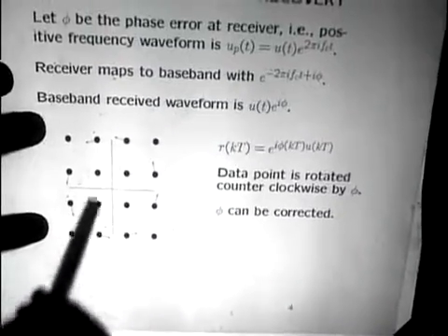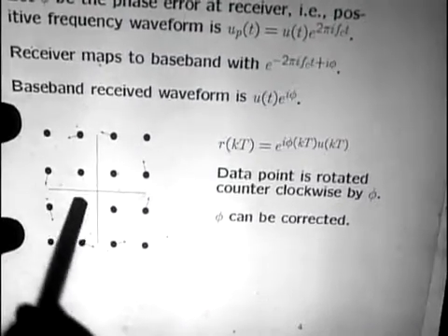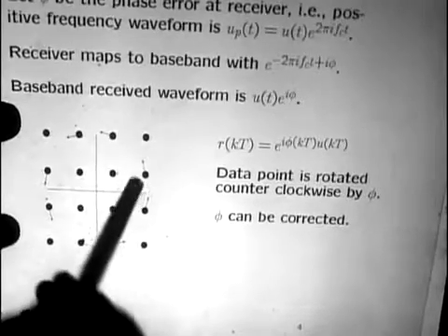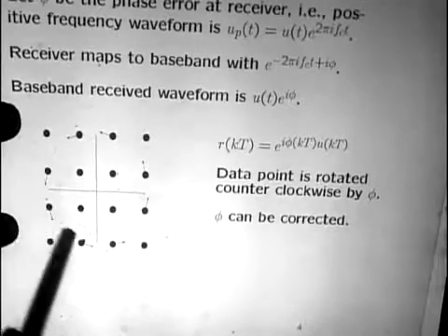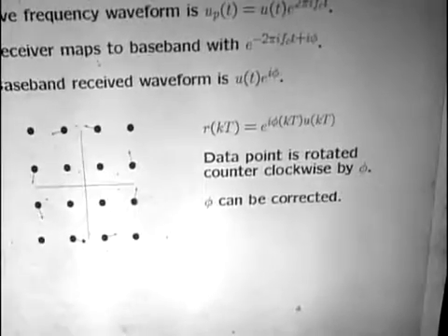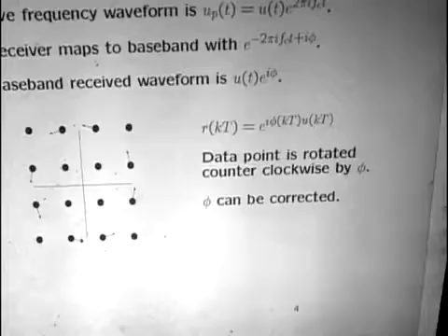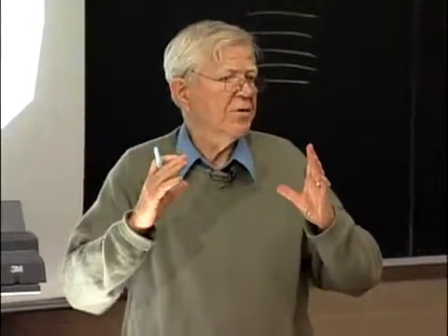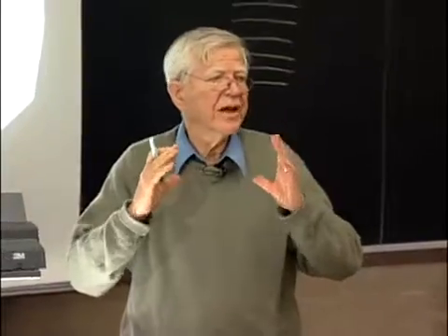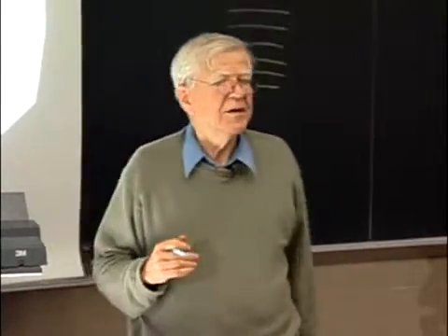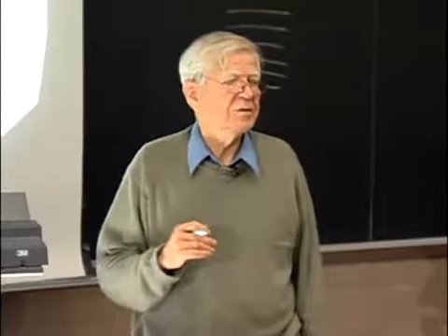You map it into an amplitude, and then you map it into a change of phase in this set of points, or a change of phase within this set of points, or a change of phase within the outer set of points. And then if, due to some disaster, you get off by pi over 2, it won't hurt you because the changes are still the same except for the errors that you make when this process starts. Okay?